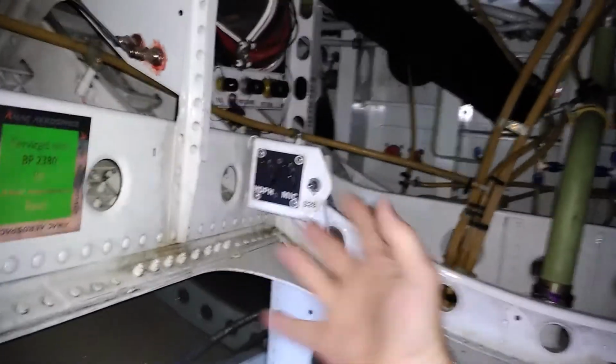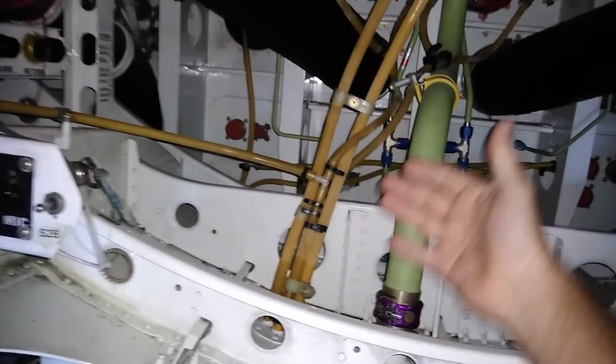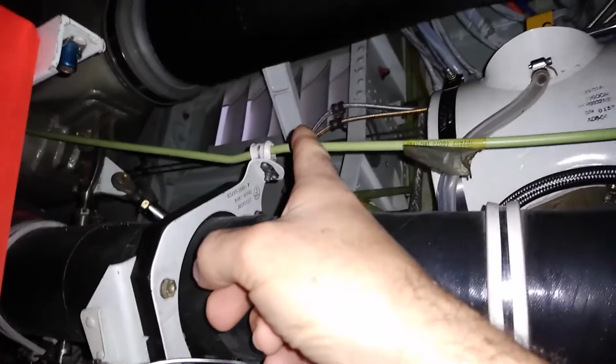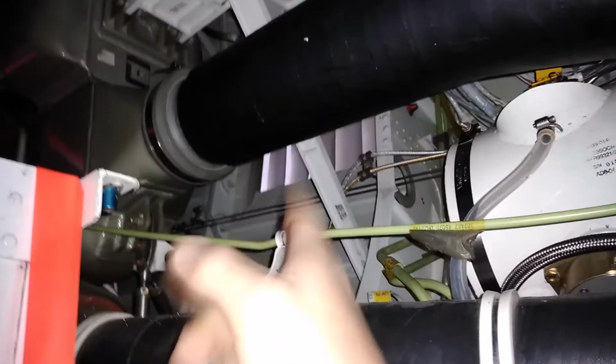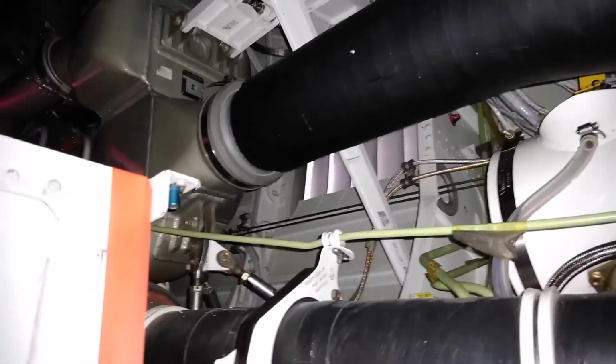it eventually gets dumped through the aft outflow valve, which is here, and the forward outflow valve, and both of them vent overboard into the aft equipment bay, sweeping under the wing, carrying any vapors, and ultimately leave through that vent, that grill. You have one there, and there's another one on this side. Now let me turn the light off so it can show itself a little better. Anyways, point is, you have two of those, one per side, and I'll show you what they look like on the outside.